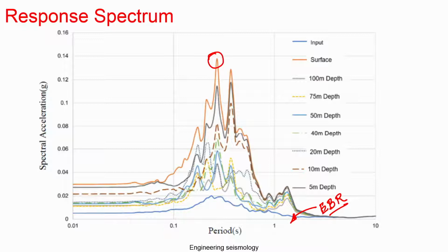That means you will get a different time history of the data with respect to depth, as long as you have change in the material density, stiffness and Poisson ratio. If there is no change, you may get the same; only if the distances are very large you may get a difference, but otherwise for shorter distances it will not have any change.